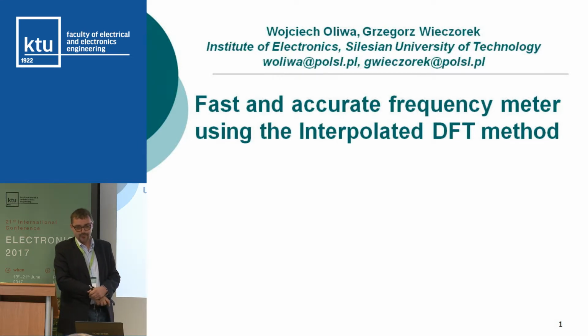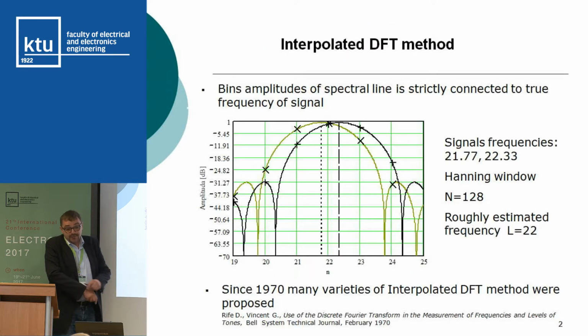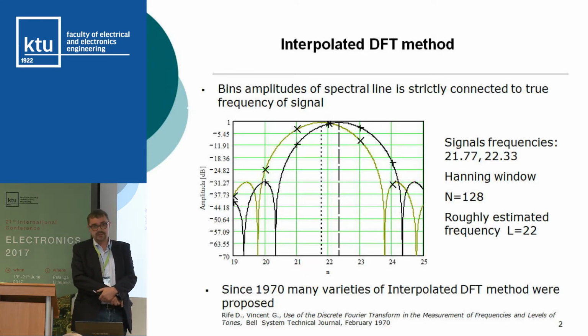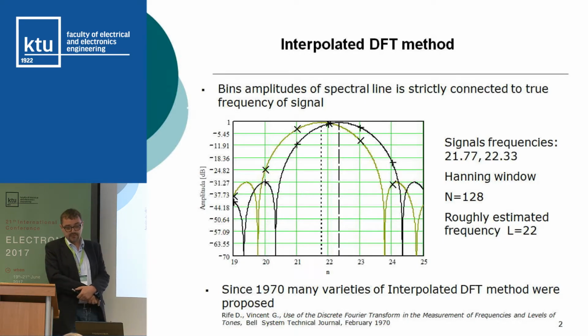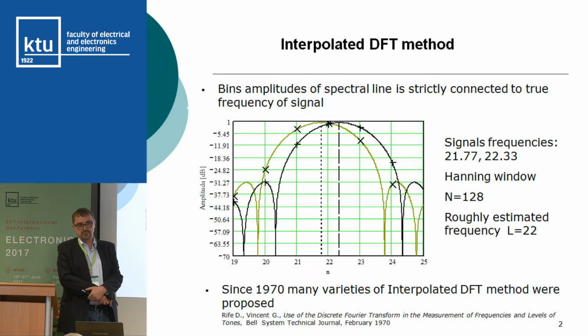I want to show you my and my colleagues' work on the frequency meter that uses the interpolated DFT method. First, I remind you or introduce you to the interpolated DFT method. Using only the discrete spectrum obtained after making DFT to estimate frequency has a very poor resolution. Simply, it is only the index of the maximum point of the spectral line.